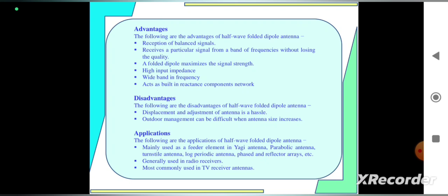The directivity of the folded dipole antenna is bidirectional, but because of the distribution of current in the parts of the folded dipole antenna, the input impedance becomes higher. However, the radiation patterns of both are equal. The radiation pattern of the folded dipole antenna and the conventional dipole antenna should be equal. Okay, I think you are all clear now on what is meant by the folded dipole antenna.